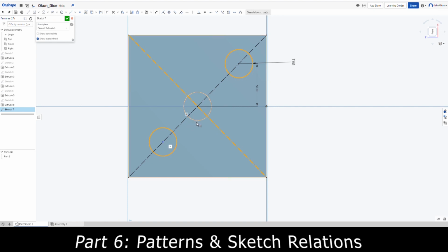So if you decide you want to choose this one, the number would change to number 4. This is helpful because if you're going fast, you can make sure that you know how many objects you've selected. And as always, if you want to clear selections, you can select the space. You can click the space bar on your computer keyboard, or you can also just hold down the shift key and deselect whatever you want.